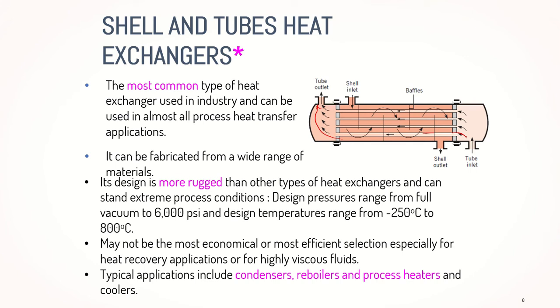So it may not be the most economical or most efficient selection for heat recovery applications for highly viscous fluids. The reason is that, as you can see, we have tubes here. If we have a very viscous fluid, the tendency of the viscous fluid to foul inside of the heat exchanger would be higher. So we will need more time, more maintenance, and also more cleaning time.